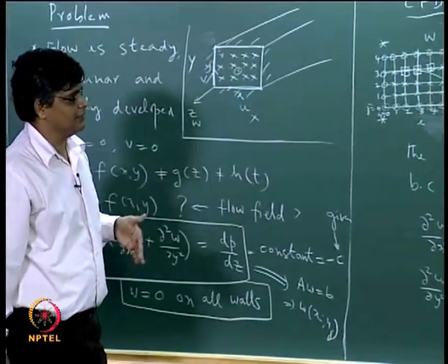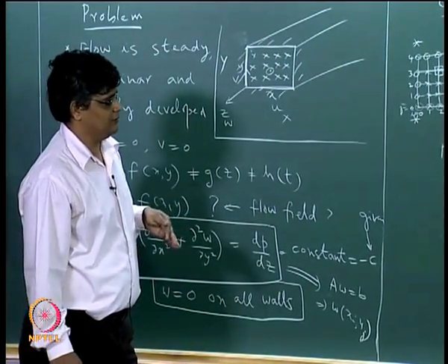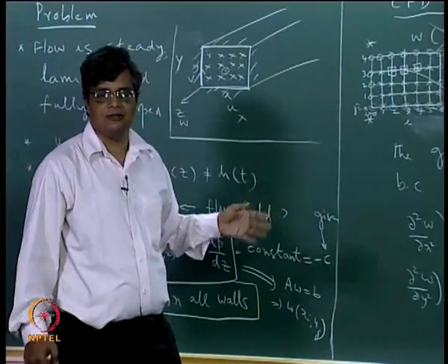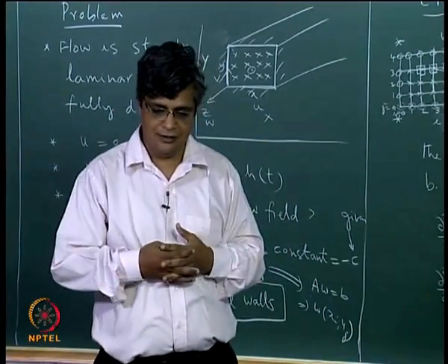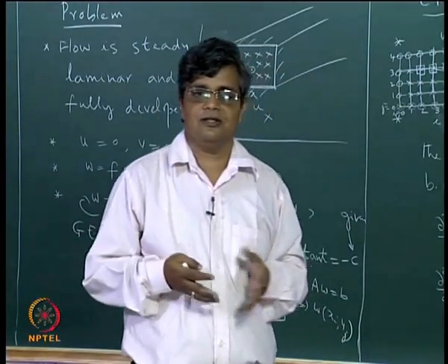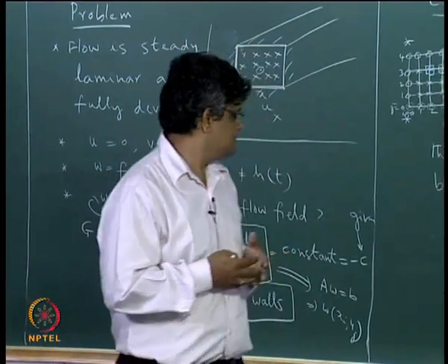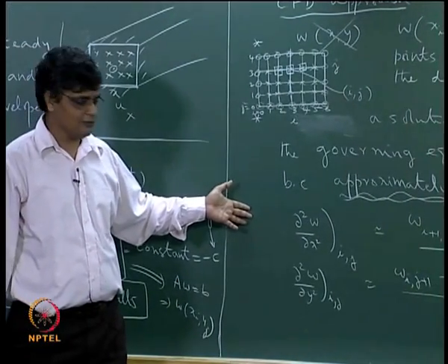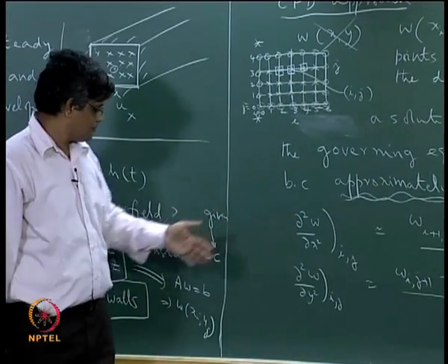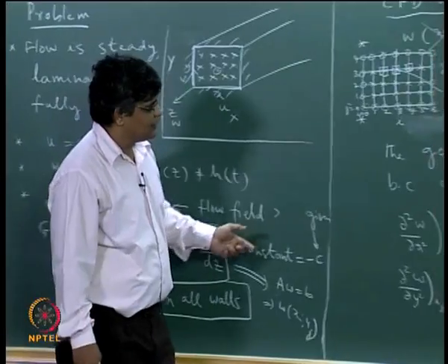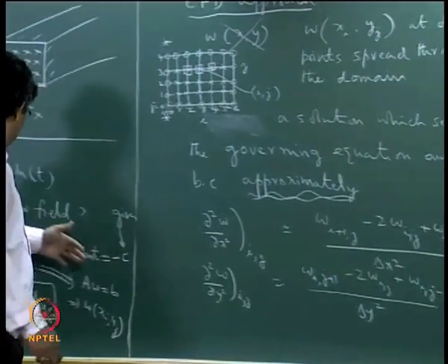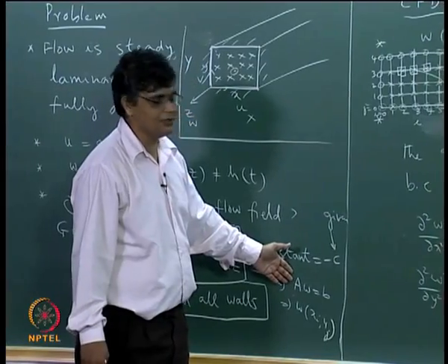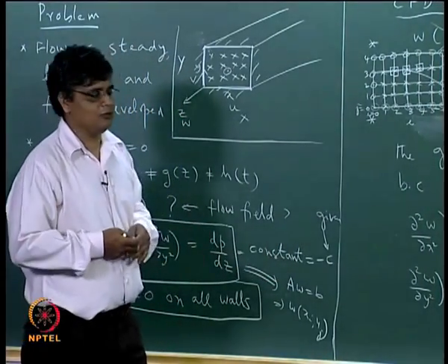So this is how the CFD approach works, and we can see that in the process of generating the solution we have not really used a lot of mathematics that we are not aware of. These finite difference approximations are fairly well known, and the substitution of this and conversion of this into the matrix equation is just a question of good bookkeeping.